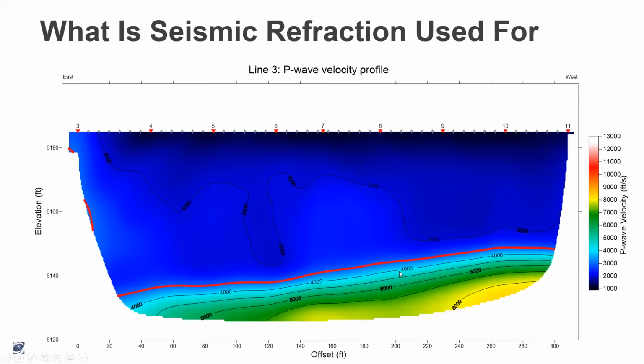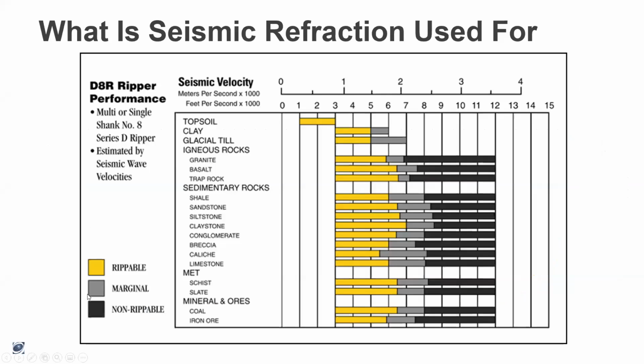And the other example that I'm presenting is for measuring the depth of fill. So this is a site that was an old smelter, and we knew that there was 20 to 50 feet of fill on top of a claystone bedrock. And we can see from the results, we have this really homogeneous top layer and then a rapid increase in velocity. By using adjacent boreholes, we're able to determine which velocity likely corresponds to the top of bedrock. That's what we highlighted in this red line.